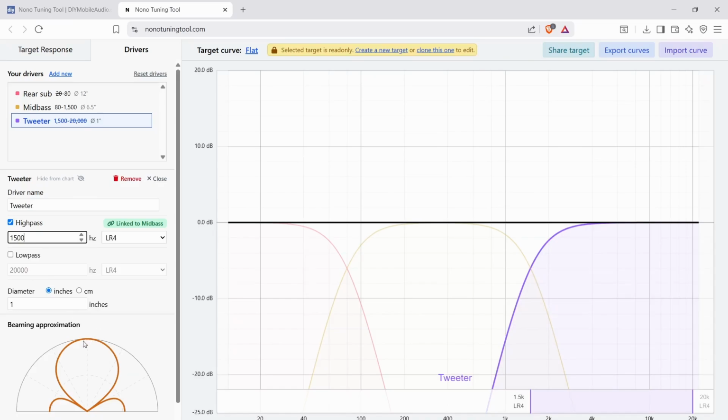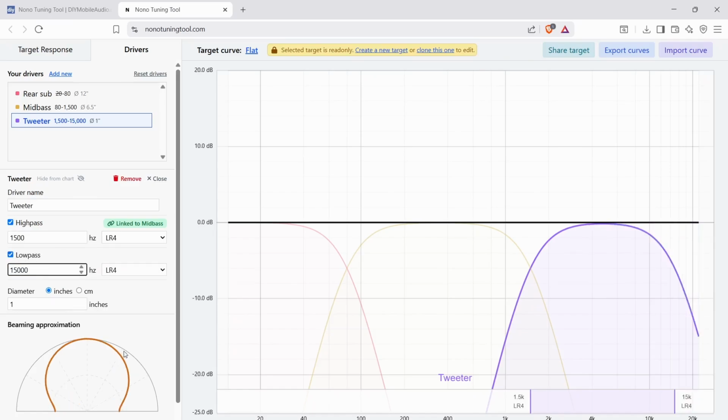That's pretty common for a tweeter. And likewise, if you take this, say, to 15,000 hertz, which is about where some people can hear cleanly, you can see that the response is a little better here, up to about 30 degrees. This is why it's usually good to mount a tweeter either on axis or nearly on axis relative to your ears, or bounce it off of the windshield, so that direct energy at 0 degrees bounces off and reflects into the listening cabin area.